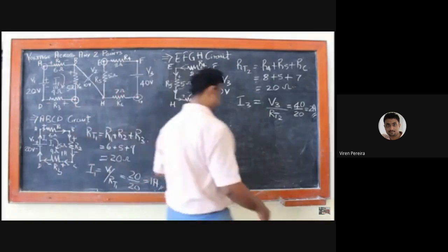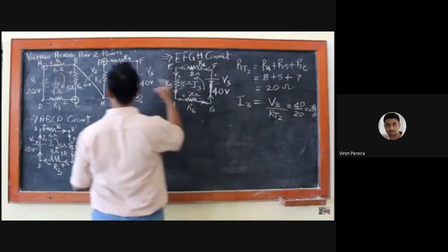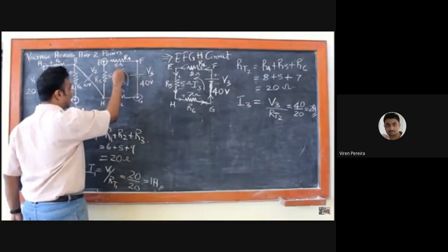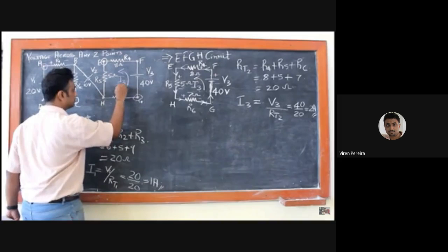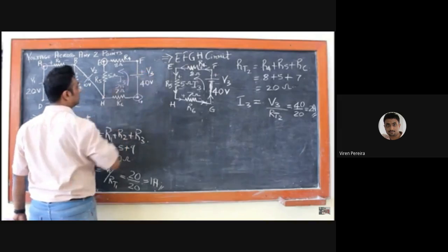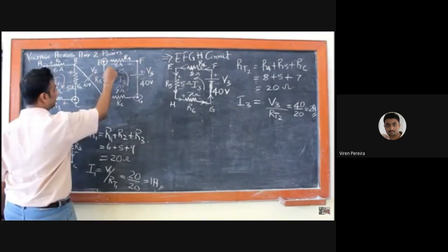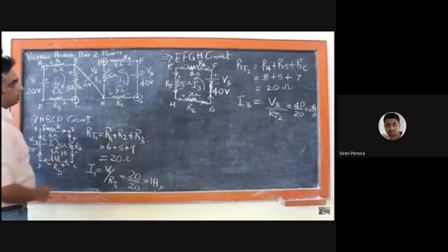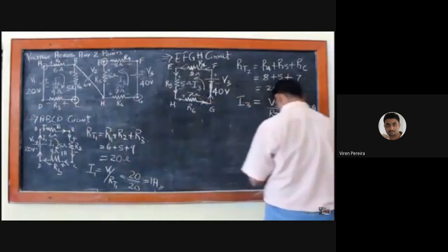Now, in the same way, I have to put these values. Here I3 is in the anti-clockwise direction. I3 value equals how much? 2 amps. Again, my signs, positive, negative. Again here, positive, negative. Again here, positive, negative, positive, negative. So I inputted all the values. Now after this step, you basically have to find out the voltage across VC.